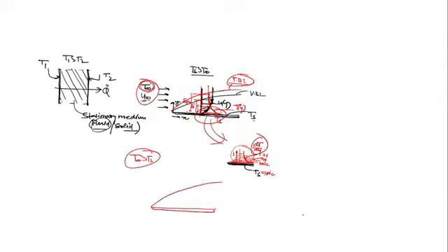The velocity profile will be as it is. Its velocity boundary layer will be as it is, because the velocity profile will simply form because of when velocity becomes 0. An arrow is used only in the case of momentum, because momentum is a vector, but heat is not a vector. Temperature is not a vector quantity. Temperature is a scalar function. So velocity I have shown here.